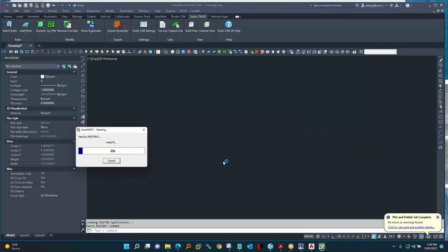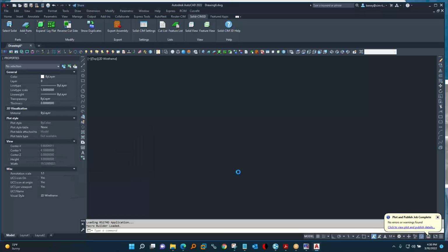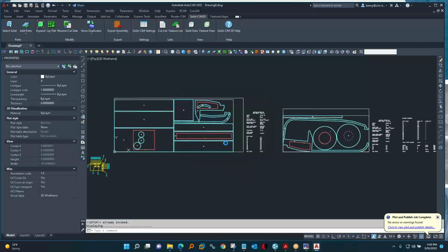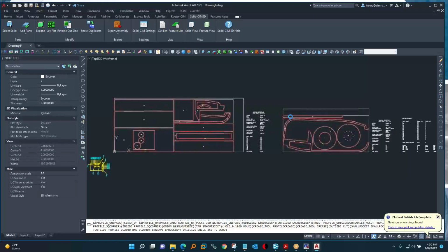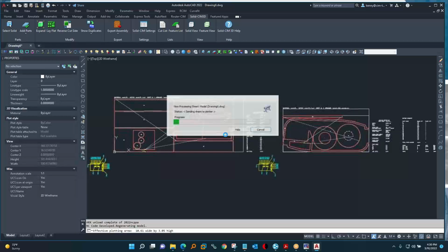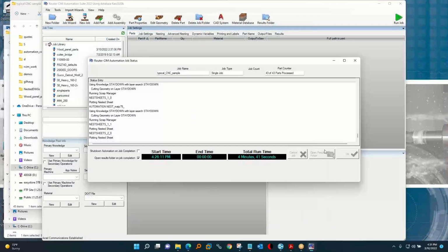And what that multiple stock control is, I can tell it I have 1/2-inch material, 3/4 material. I get different sheet sizes, 4x8, 5x10, 5x12, and I can nest by yield or by price. So that's why we see a big sheet here and a small sheet here. So it did 5x12, most of that, and then the rest they put on that sheet.